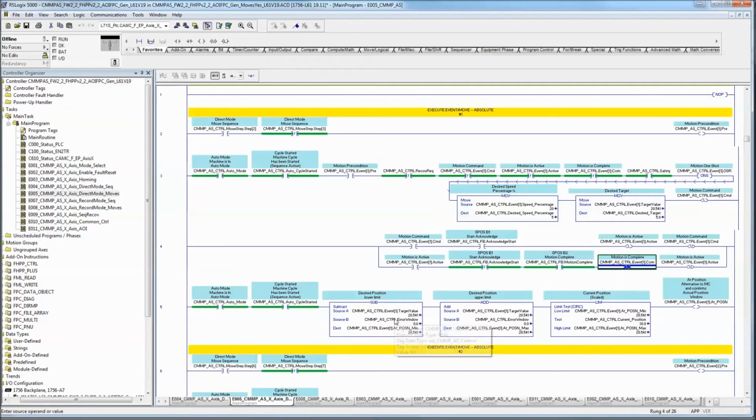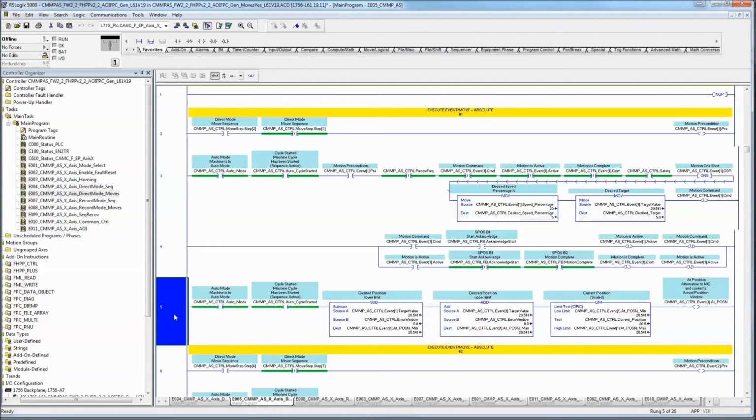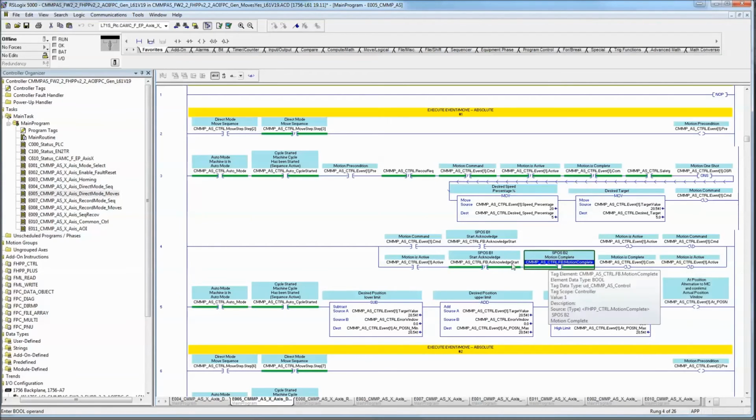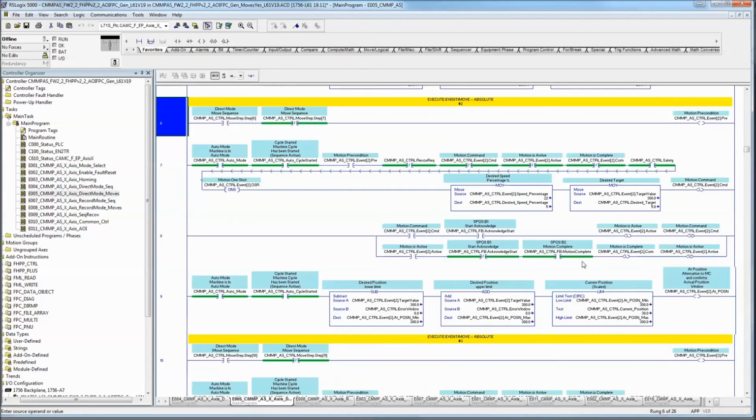If you want to close the window around something manually, I can do that with this code right here. I always like to create my own window to be certain that I'm at position, because the motion complete is typically, in most controllers, based upon the theoretical motion complete. And that's just move one, and then it's the same copy paste for each move.